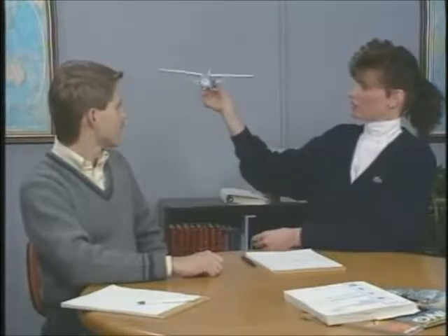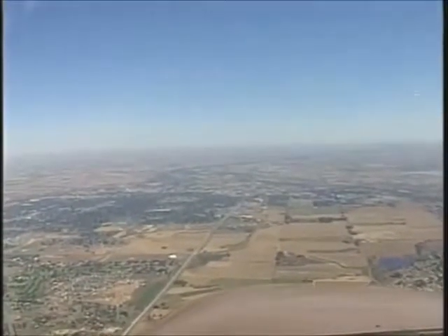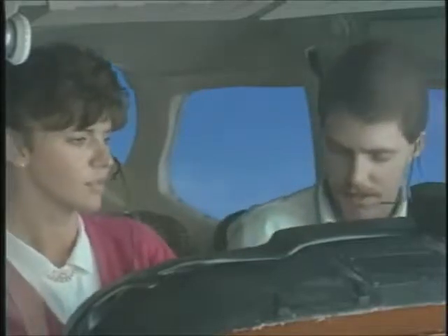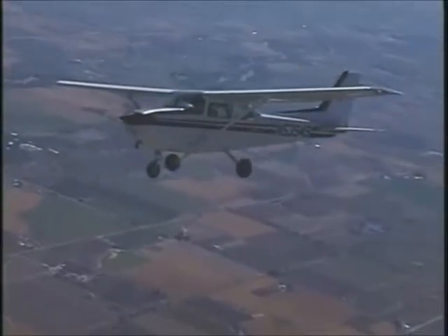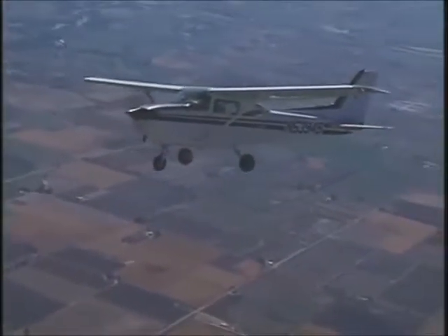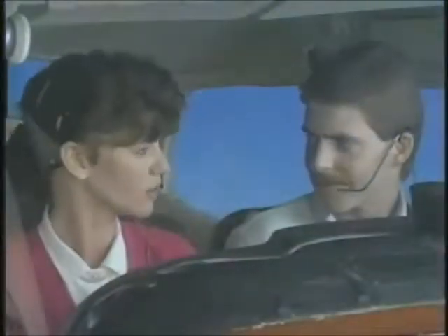The ground training portion includes instruction in the areas of stall awareness, spin entry, spins, and spin recovery techniques. Then, as your flight training progresses, further emphasis is placed on stall recognition and recovery, and realistic distractions are introduced during flight at critically slow airspeeds. It's important to remember that actual spin training is not required, and under no circumstances should you practice spins or spin recovery techniques without a certified flight instructor on board.